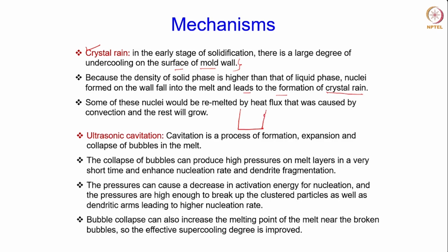So it will immediately nucleate the solid grains as fine nucleus grains along the mold walls. And if you go away from the mold wall, then it will take up dendritic or columnar kind of morphology as the thermal gradient develops, right?